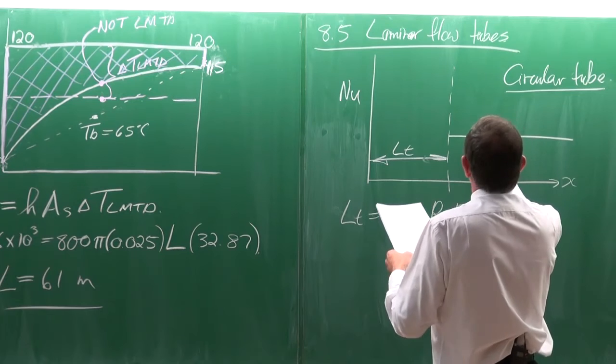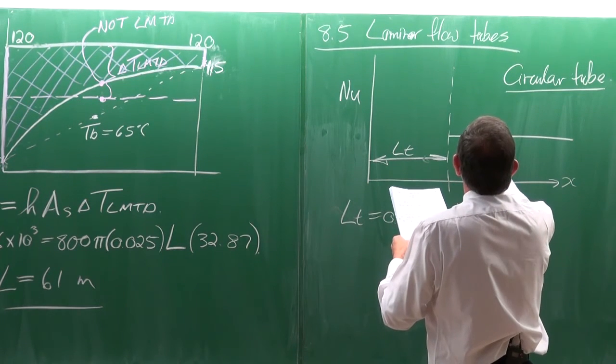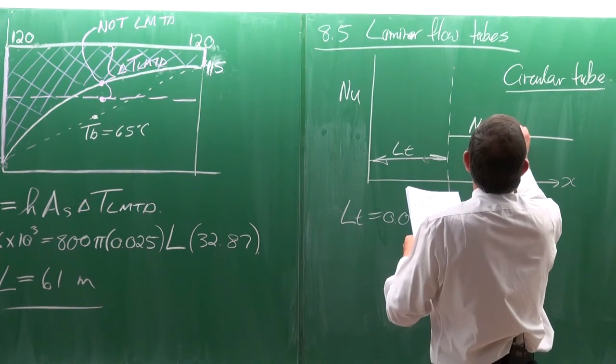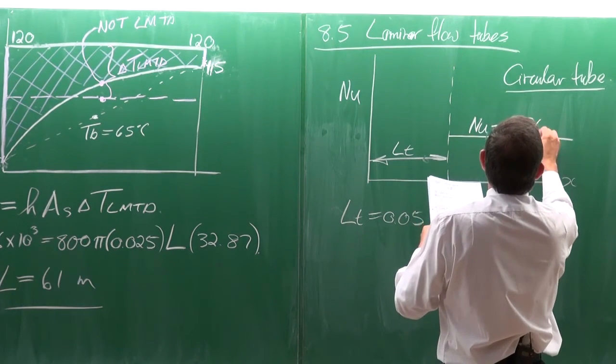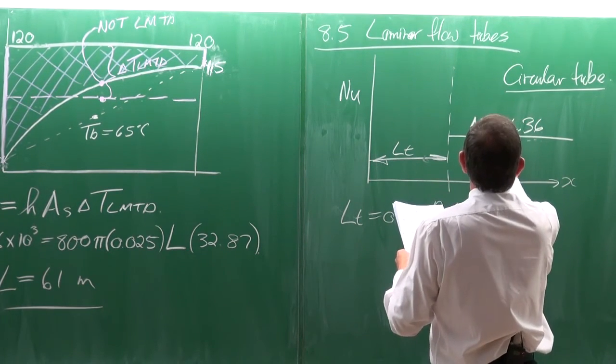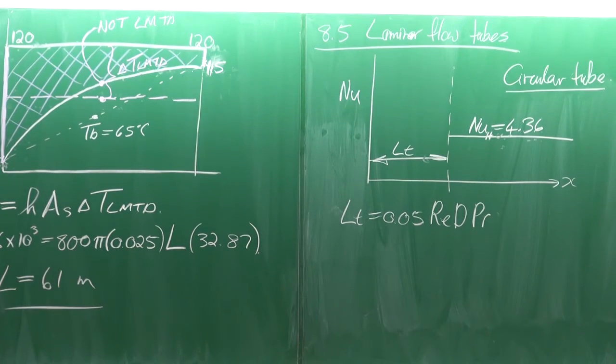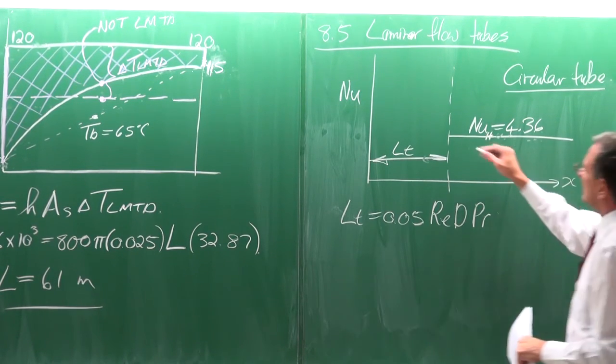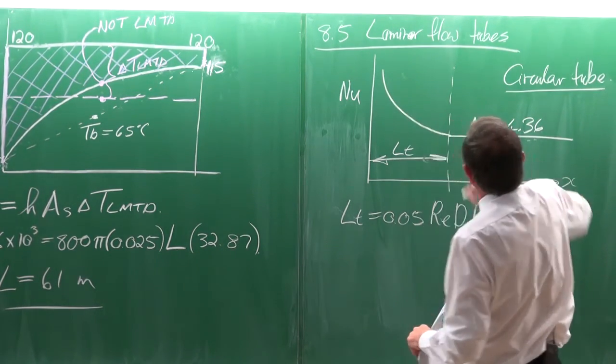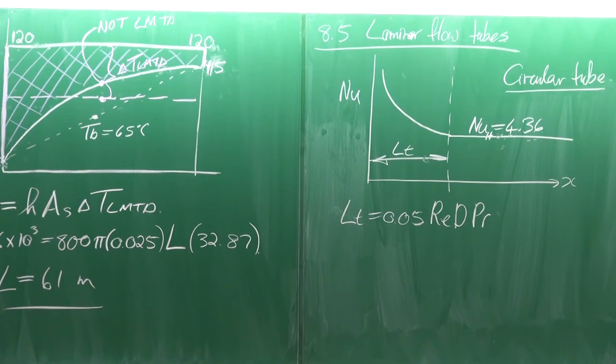And it says that the Nusselt number is equal to 4.36. And that is the H case. So it's for the constant heat flux case. Okay. So the Nusselt number for laminar flow, fully developed, is 4.36. And anybody who passed heat transfer will tell you that. So it's an important number to remember, if you want to remember it.